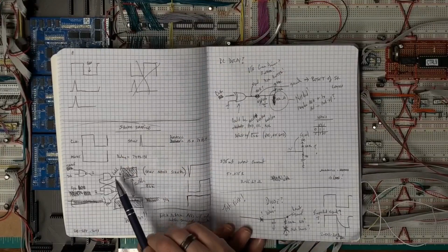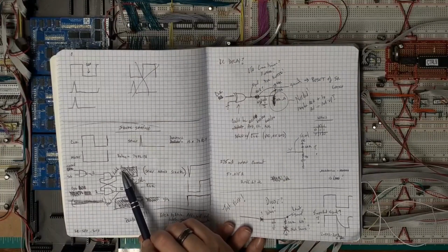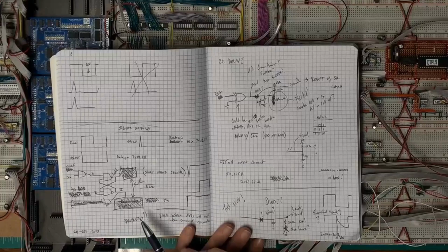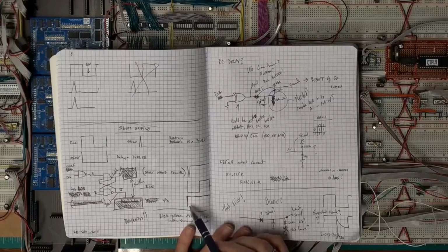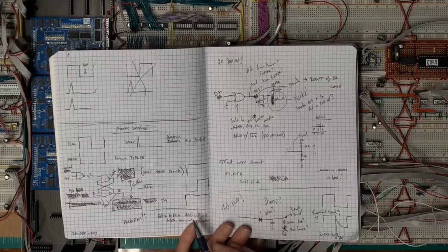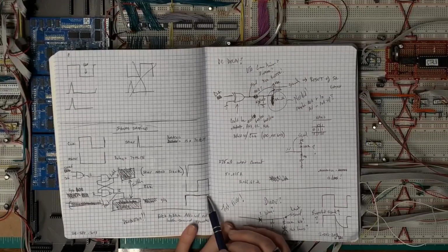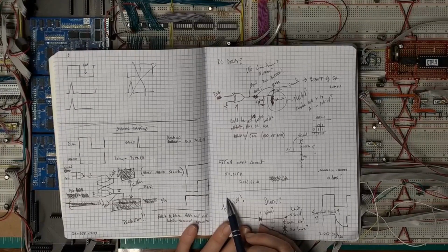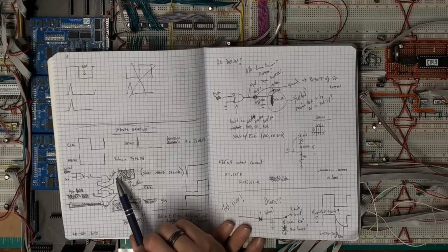I originally went down the path thinking I needed a latch in order to manage the actual latching of the ALU output and asserting that output out onto the bus. You can see I've got scribbles all over everything, trying to rethink as I go. Ultimately, what I realized was if I had two back-to-back ALU operations, I would have a signal that was high for the entire clock cycle, and then the next signal behind it would also be high for the entire clock cycle, meaning that I would never get the reset, meaning that I would never actually get the latch. That wouldn't work.